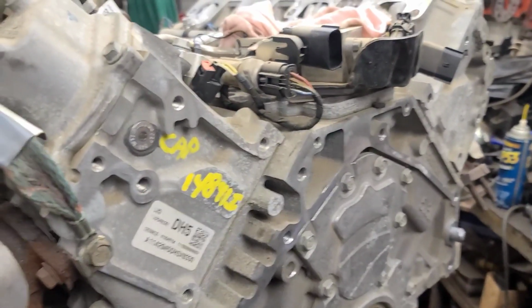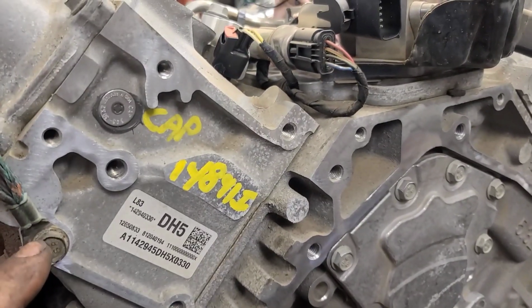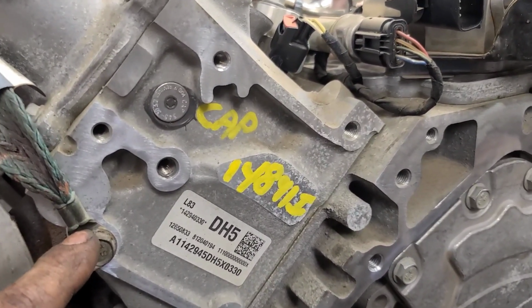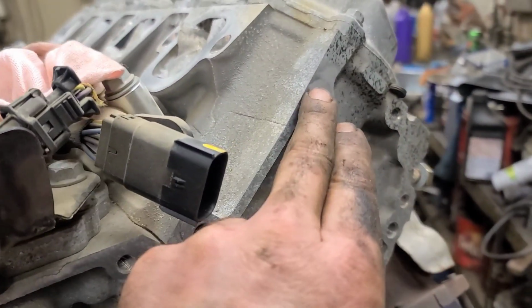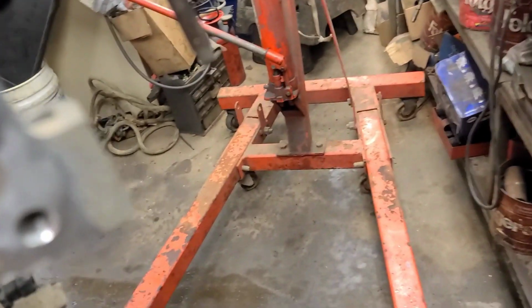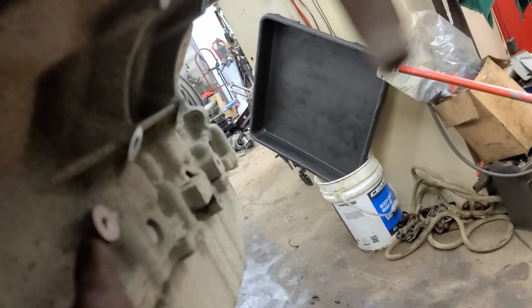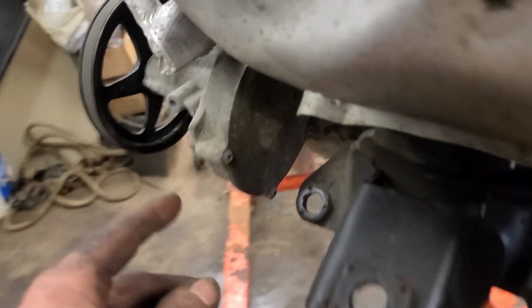So I'm getting ready to prep this used engine. Make sure you clean all the grounds. There's a ground strap here that goes to the firewall. Ground wire here. Ground wire here. There's a ground cable behind the starter, the main ground cable there, clean that. And there's another ground wire beside the vacuum pump fitting right there, clean that one.